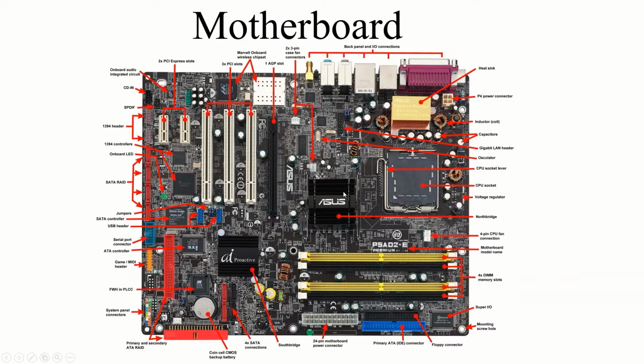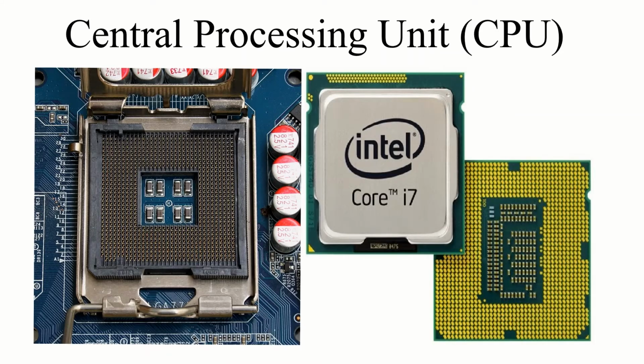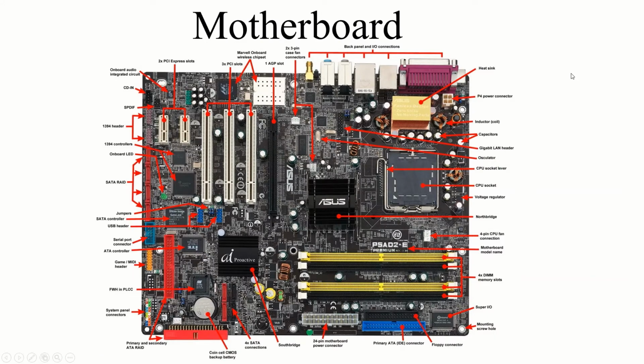This port should be available anywhere on the motherboard, but I am telling you about this one because I have shown this one. So we need to put the processor in the correct way. This arrow mark will match this arrow mark on this area, and after that lock this slot and put the silicon gel on this area. After that put the processor fan on it, and we need to lock it. There is a locking point on the motherboard.